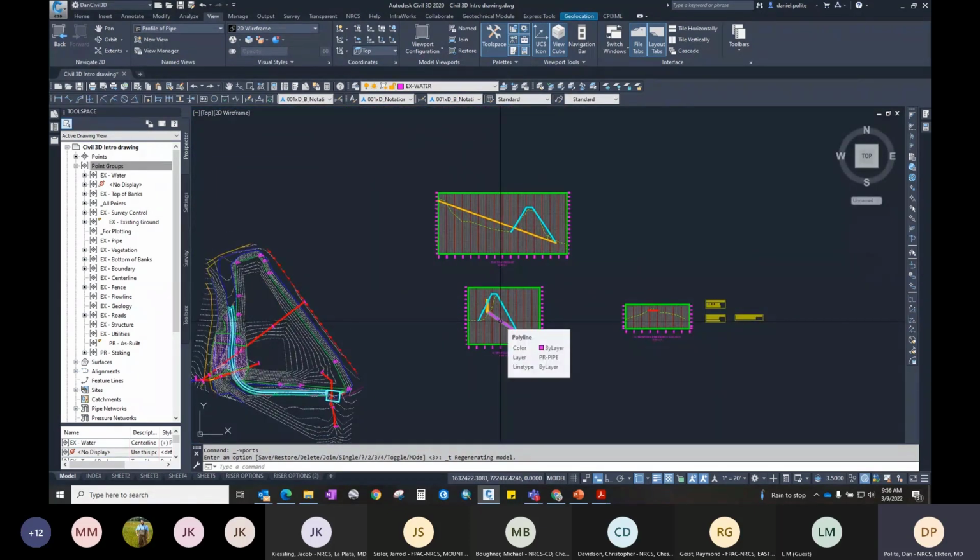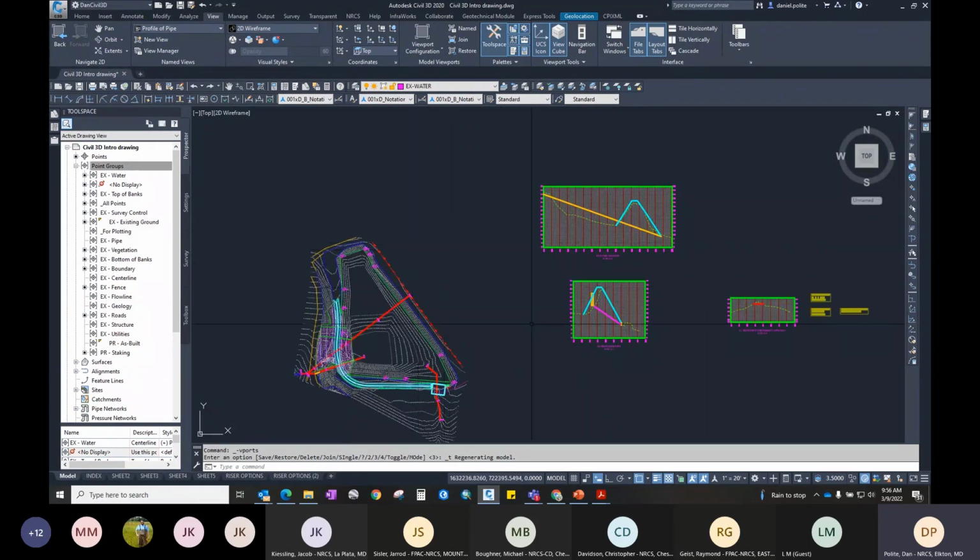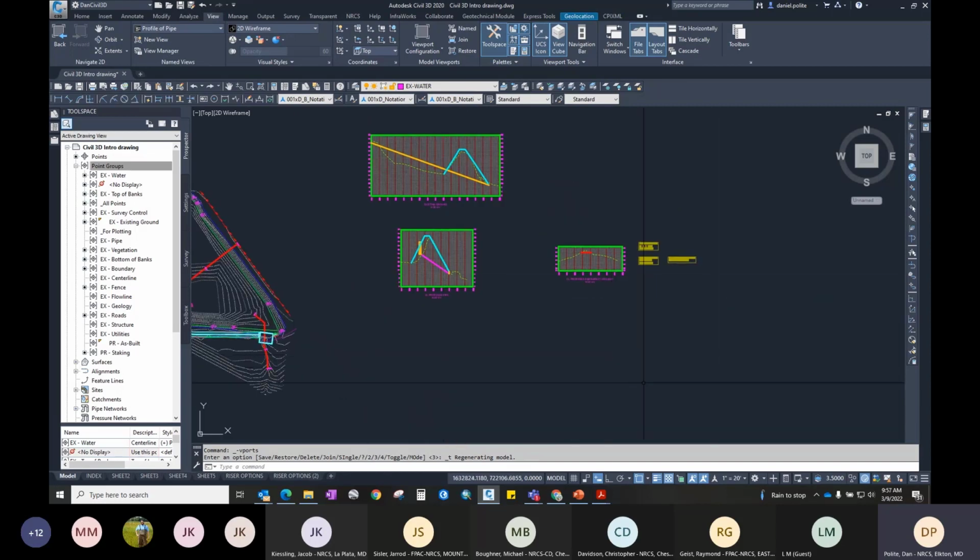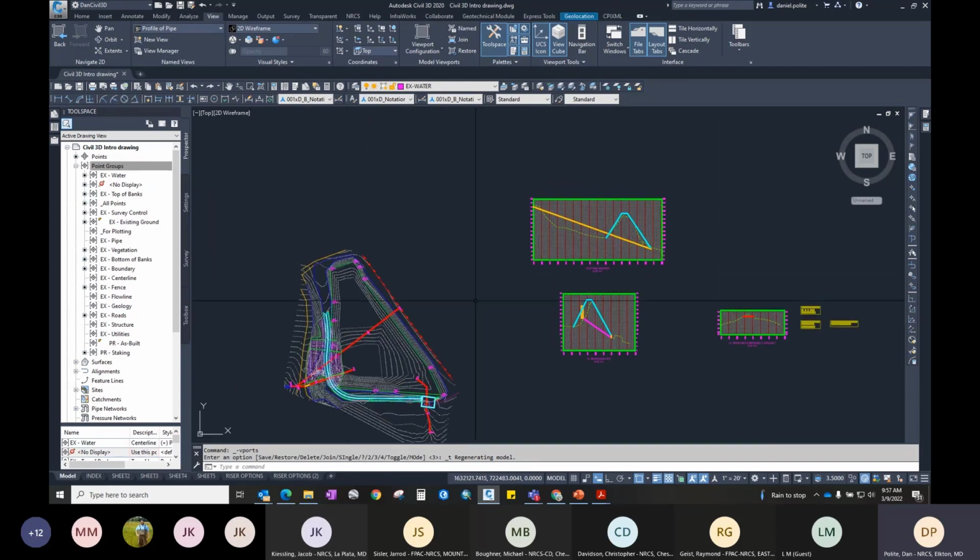So you can create a plan view and say this UCS on this, and we'll go over the UCS, and it was changed. I can create that same plan view if I wanted to turn this. So this water level is on the bottom horizontal x-axis. I can go into my plan view and make a viewport and select that plan view, and now that will turn in my viewport the way I want it to. So it's very useful in that aspect too. Any questions on that?